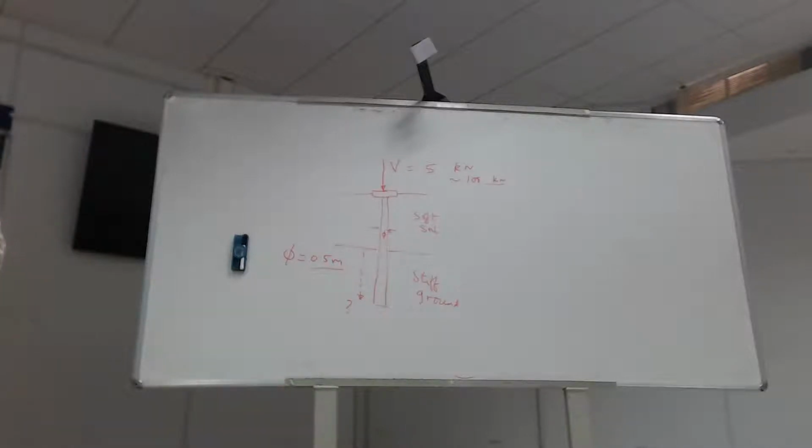We're not physicists. So when we say a half a meter diameter pile, you should have a rough idea what's the compressive strength of concrete or yield stress of steel if it's a tubular pile, and what can I reasonably apply just from a concrete point of view, let alone the soil and the load carrying. So don't just make up numbers.